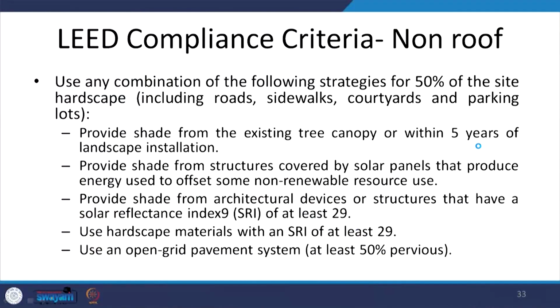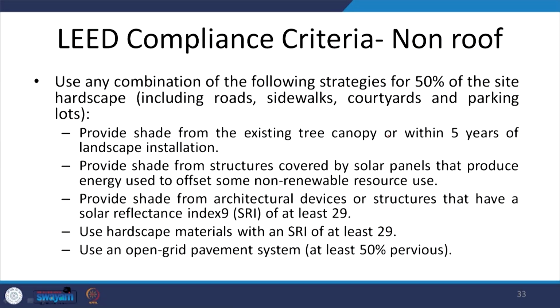If we look at the non-roof criteria, we have to ensure that at least 50% of the hard surfaces, the hardscape on the site, follows the strategies which we have just discussed. So, at least 50% of the entire site hardscape has to use a combination of these strategies. In terms of SRI numbers, at least an SRI of 29 has to be achieved for at least 50% of the site hardscape.